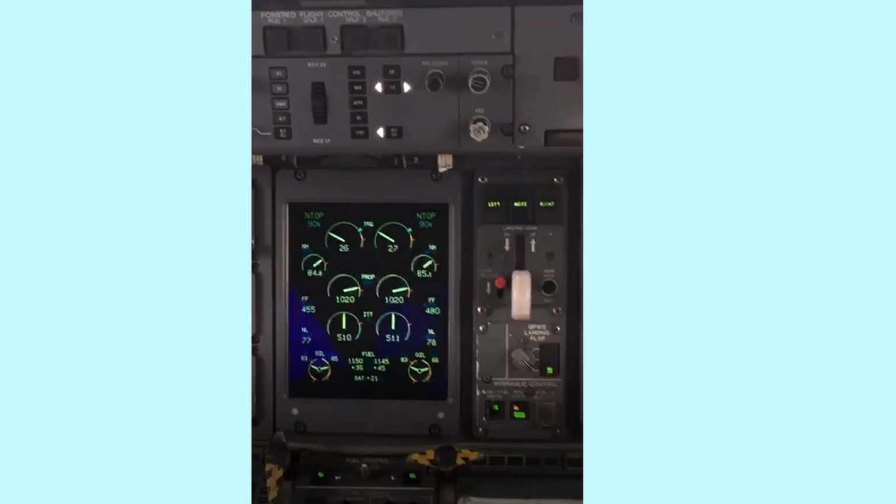And this actually happens with all configurations. I've done, as I said, numerous flights after I wanted to find out why it is that the first 2 digits of the landing weight should match the torque value in order to give you VREF to VREF plus 10. That was my main aim for this presentation, and I hope I have made it clear. It's been working out very well for me. It does work out for other people as well, so I'm pretty sure that this should be a good rule of thumb, we can call it.